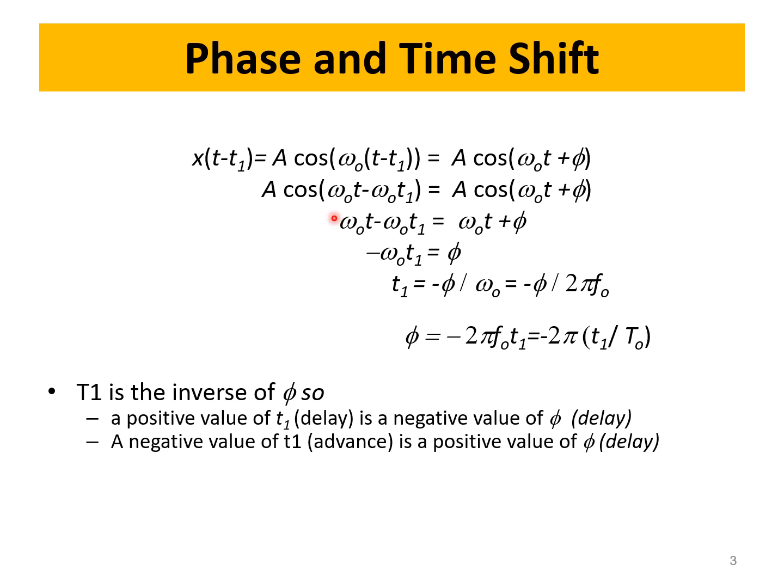If you break it down, you can ask, are they the same? If you have a time shift and a phase shift, each one of them results in the same thing, but we'd like to see the relationship between time and phase. That's the key. So we can write a cosine w0 t, replace every t with t minus t1, and introduce a phi on the other side. Originally you have cosine w0 t, that's our original signal. Now replace every t with t minus t1, and also add a phi on the other side, and let's see the relationship between the time shift and the phase shift.